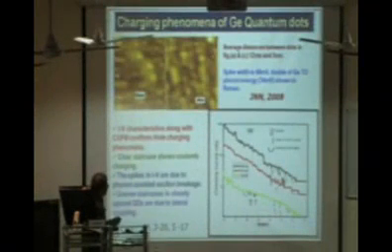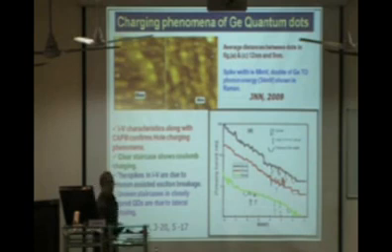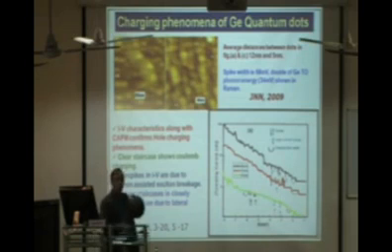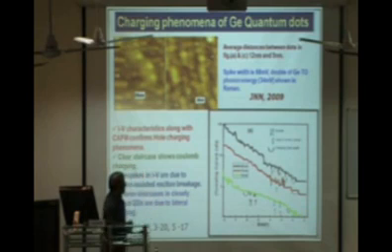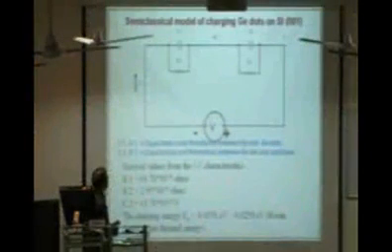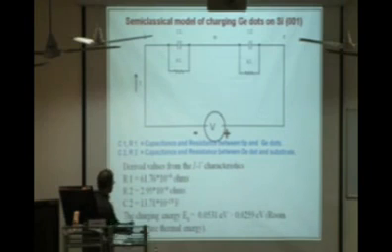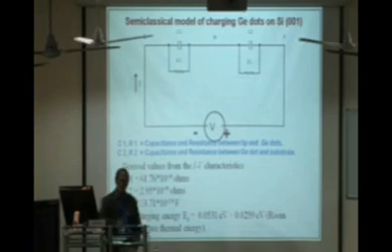In fact, as I was telling you, we also got some staircase characteristics when you could take a conducting AFM tip on one of the single quantum dots. But as you see, there are a lot of noisy things also, because these are taken at room temperature. Normally people have demonstrated with low temperature STM experiments a very nice IV characteristic with a lot of staircase. But ours was mixed with a lot of other noise also. We found the charging energy is about 0.053 electron volt, which is much more than the room temperature energy. That's why it could be achievable at room temperature. That depends on the size of these quantum dots.